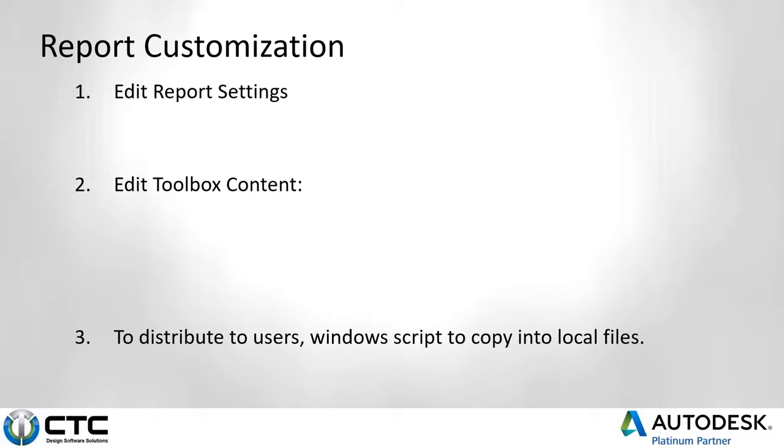The stuff lives on the C drive, and it lives really deep and really buried in hidden folders like ProgramData and your user's AppData folder. So whatever your enterprise setup is, if you have a network profile, or what CTC has been recommending for a few years now, is having a local setup. Basically this means there is a master computer somewhere that has all the settings on it. It'll push those files up to the server, and then the server will download those all automatically onto everybody's user computer so that everything's on the C drive.